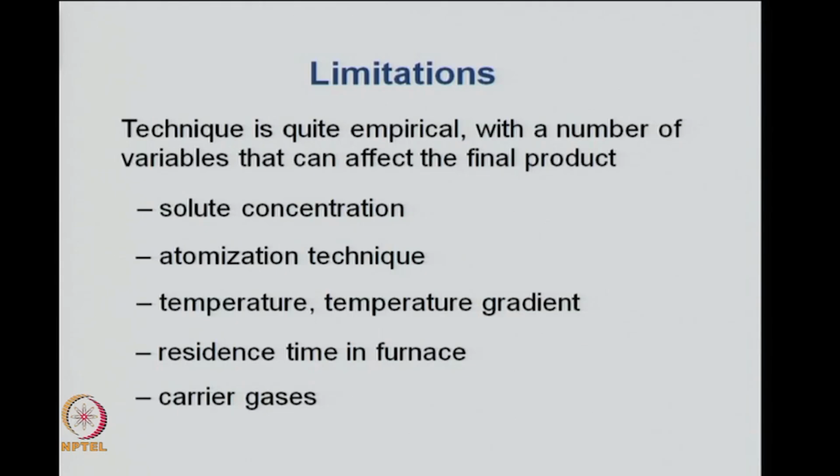Are you using very high pressures, or are you using an ultrasonic atomizer? So, there are various types of atomization techniques, each of which will have its own mark on the process. Then, what is the temperature at which you are drying or sintering? What is the temperature gradient? What is the residence time in the furnace?